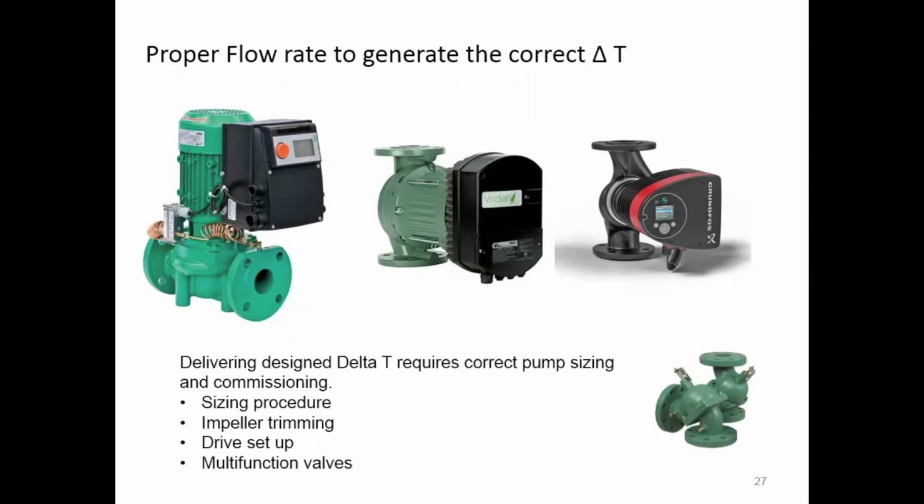And of course, in most applications, we're still seeing the multifunctional valves, also referred to as triple duty valves because of some of the other functions. But in addition, in a lot of cases, even with the drives, there is a balancing valve associated with the pump to make sure that we're setting the proper flow.